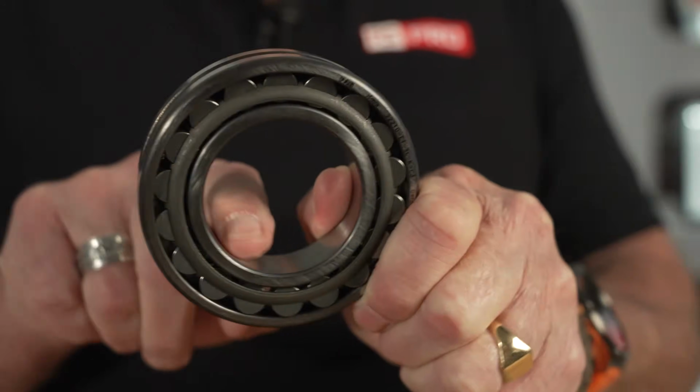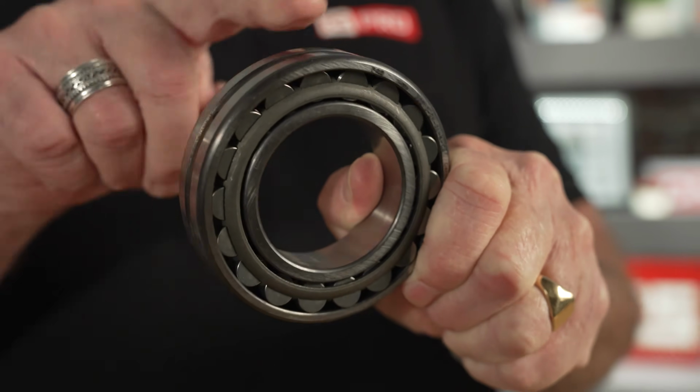This is indicated by black marks on the outer ring or on the inner ring. If you put a new bearing in on that existing housing and shaft, it will try and conform to that pattern, which will put extra stresses on the inside, and the bearing will fail quicker than the previous bearing. And that will happen continuously, just worse and worse.